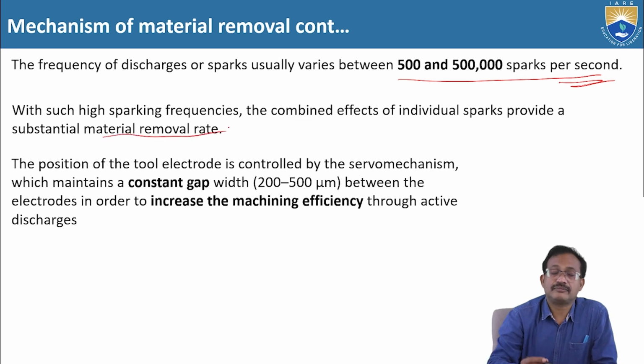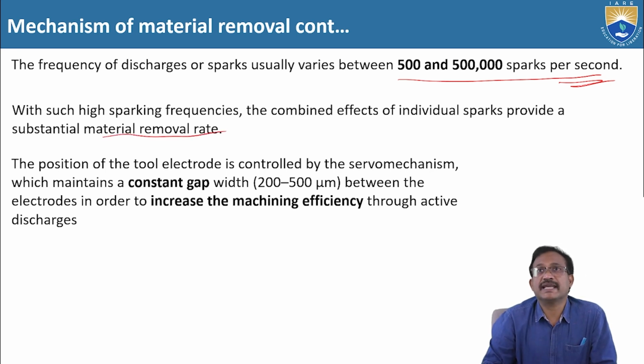Just imagine, in 1 second 500 to 5 lakh sparks, nothing but strikings. Obviously the material of the workpiece will be subjected to high thermal stress, and at the same time the material will also vaporize, leading to material removal.